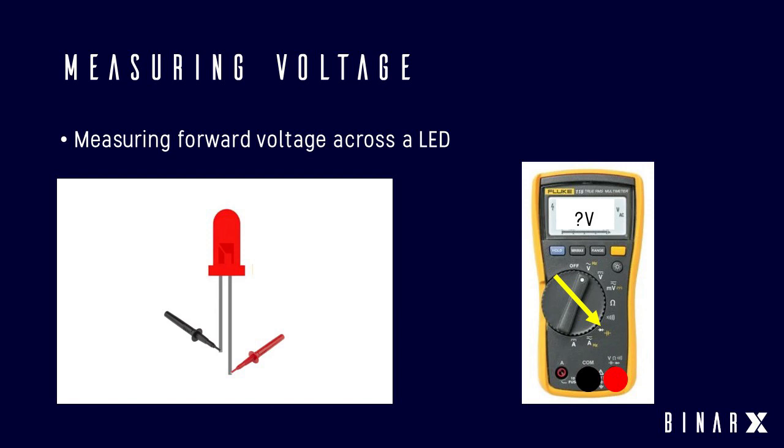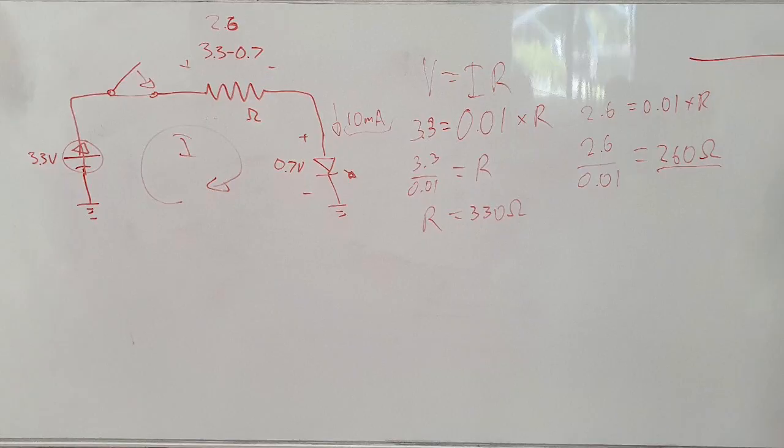You need to do 3.3 minus the voltage. Yes, but I'm going to get there. So I equals V over R, and we want to calculate the resistor that we need to supply 10 milliamps to this LED. The way we're going to calculate that is first by rearranging I equals V over R to solve for R. Has anyone got their pieces of paper? If you want to do it old school. A little bit of algebra. It's not quite as fun as plugging things in, but unfortunately it's a big part of electronics.